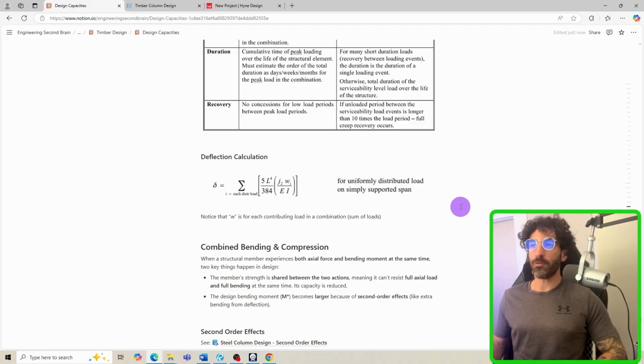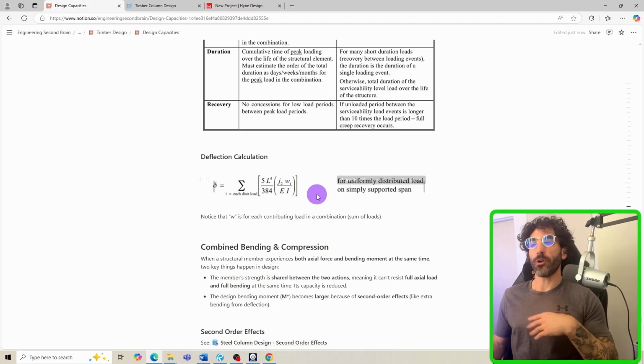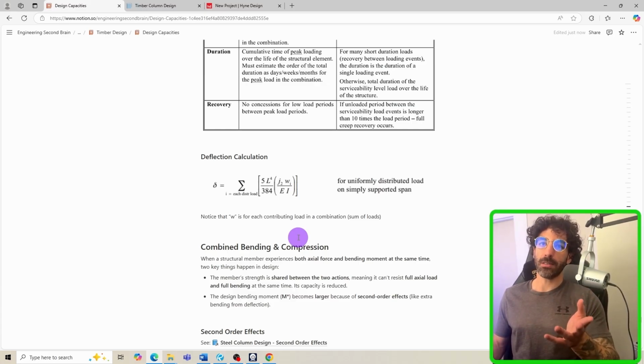And as I said before, that means if you have a J2 factor of 2, you double the deflection. If that J2 factor equals 3, you triple that deflection. So if your J2 is 2 and then you worked out the deflection of 10 millimeters, you can expect another 10 millimeters extra of deflection in that beam.